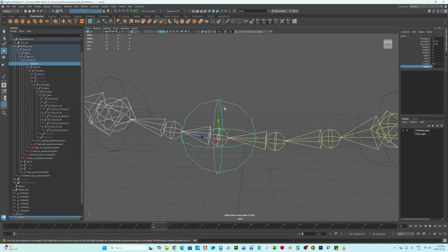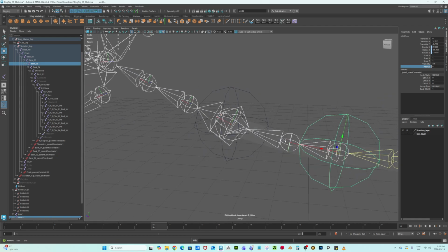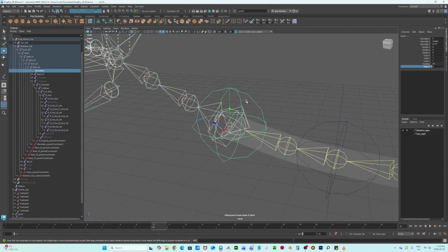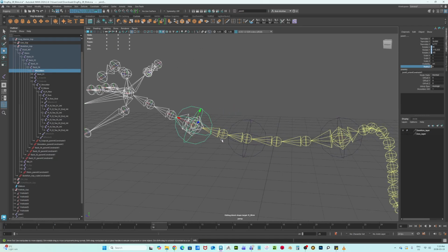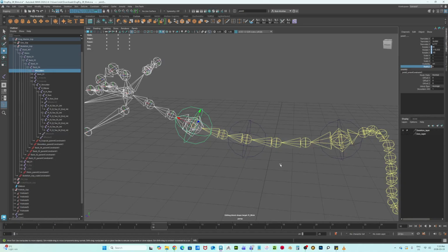So if I grab that joint first, then this one, I hit G, it'll repeat the last tool command. Grab this one, and then this one, I can hit G again, so it's lined up as well. So their axes are lined up perfectly.